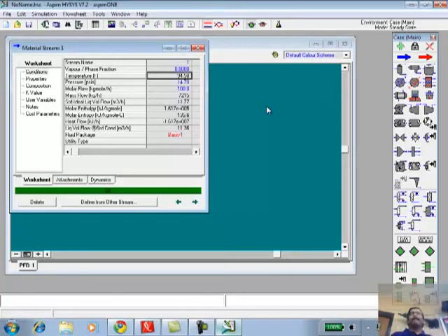After you look up the species, the vapor fraction is 0. Set the vapor fraction to 0 because it's a mixture. It's a mixture of 7 components, and that mixture contains equal amounts of all those 7 components. If I take that mixture, ethane, for example, is the first component, the most volatile, so it will start bubbling first. And octane is going to be the last one to be driven off.